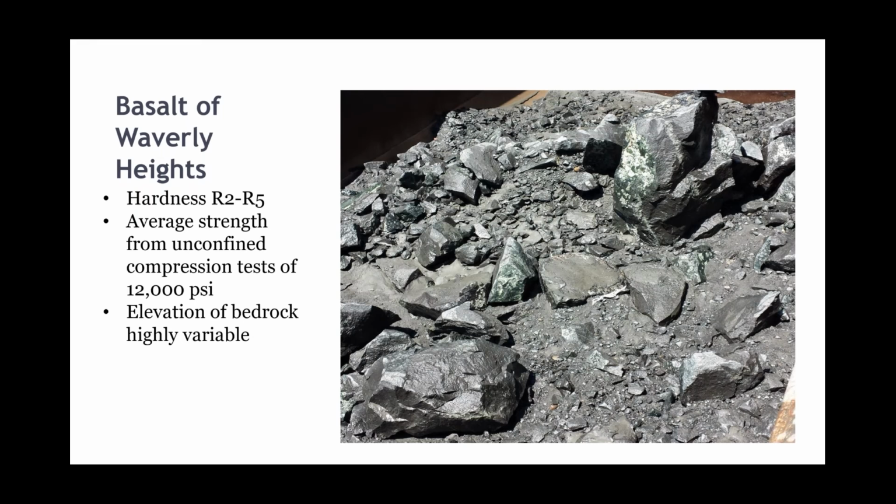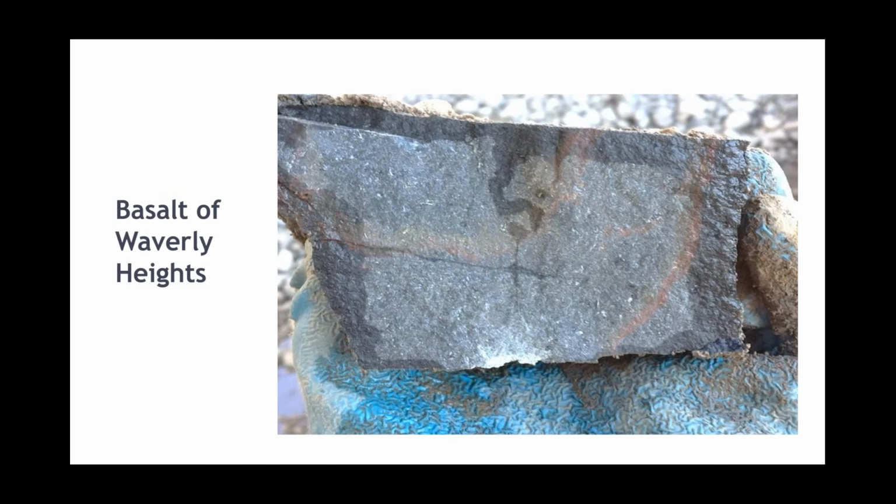Certainly we recognize from the borings and the geologic environment that the top of bedrock is highly variable. And that's another reason why the additional testing by having an engineer out on site paid dividends. And I'll just reiterate, the conservative design assumptions that were made originally, that's only conservative for design. For the overall project, it's actually unconservative. One more photo of the basalt after being busted open with the geologic pick, really, really high quality rock.